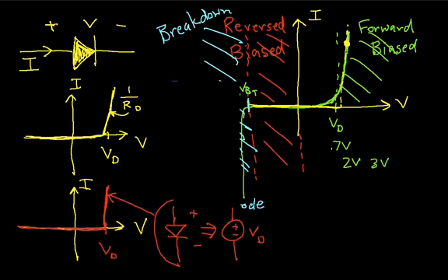When the maximum voltages that you're going to use are much larger than V sub D, quite often you can ignore that V sub D and come up with an even simpler VI curve, which looks like this. You assume that V sub D is small. In fact, it's small enough to be insignificant. So your VI curve just follows the axes here. Okay.